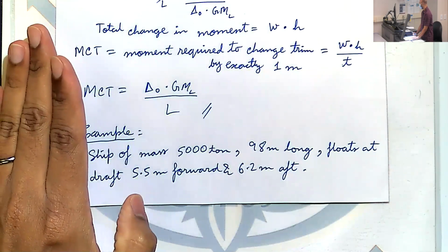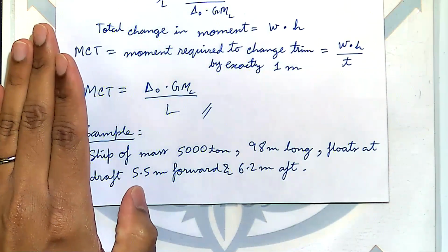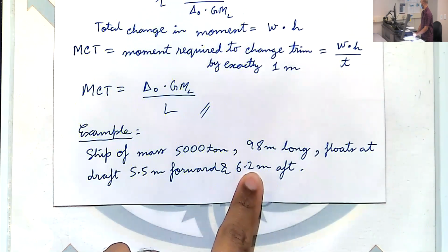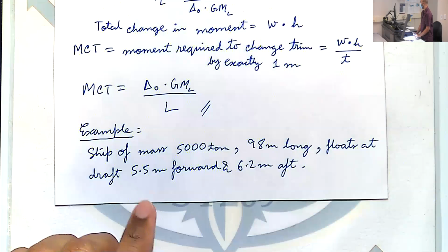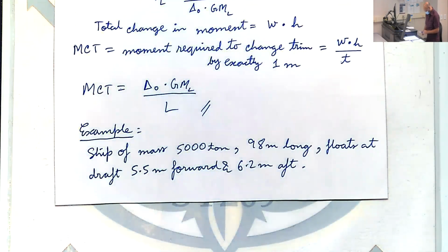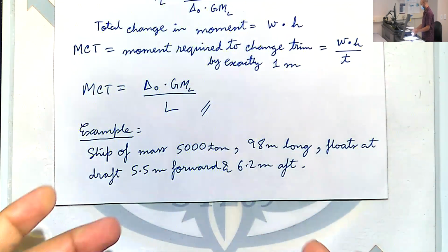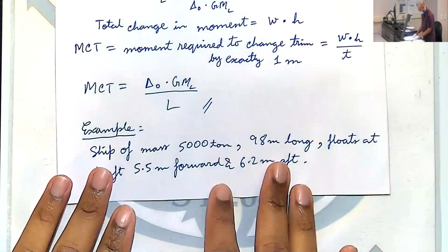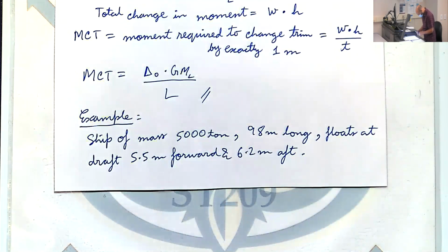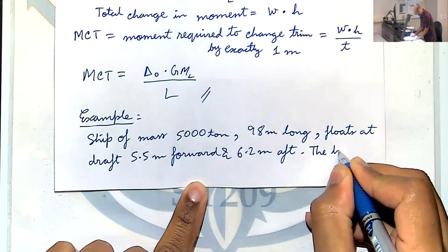Who's more immersed, the forward or the aft? Oh, the other way around, my bad. Exactly, the aft is more immersed and the forward is less immersed, so we have it nose up. Sometimes I mess this up as well, but just think of who is riding deeper in the water.